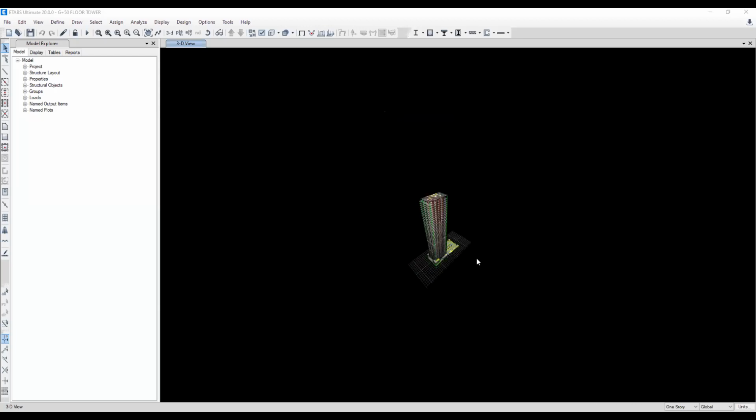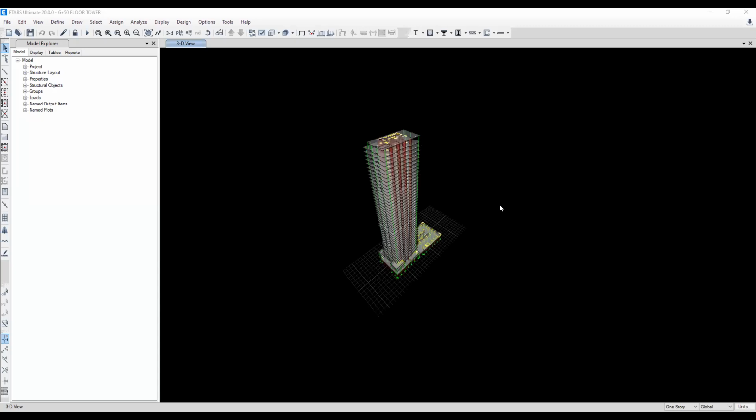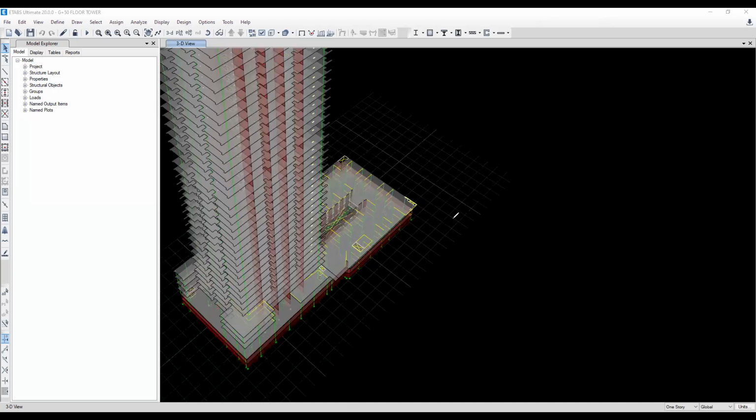Inside that, you will see what kind of new considerations we have to take. Whenever we are going for a high-rise and tall structure, we have different structural forms. Like here you are seeing we have the podium level also. Podium level means the car parking, right, Karim? We can use this for parking purposes. So for this, we have a different approach to design and analyze high-rise and tall structures.